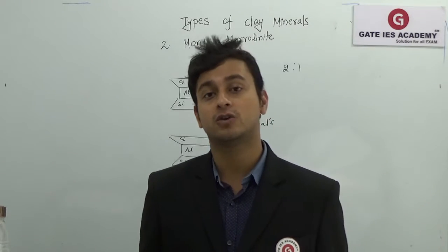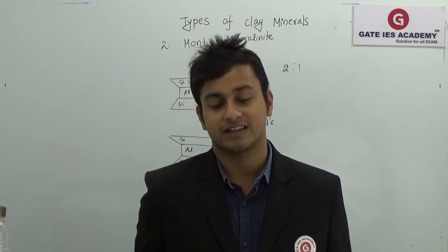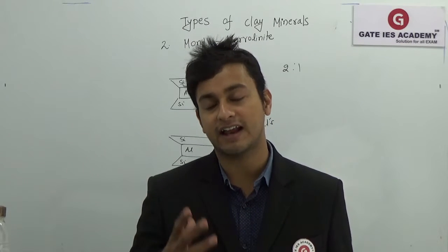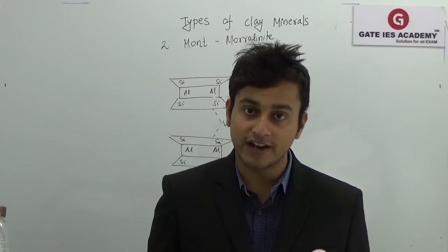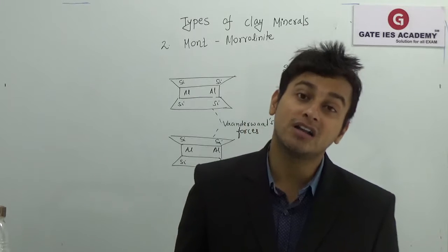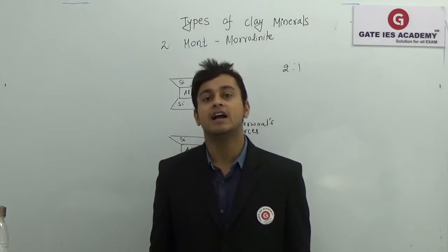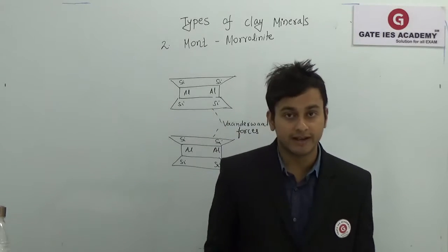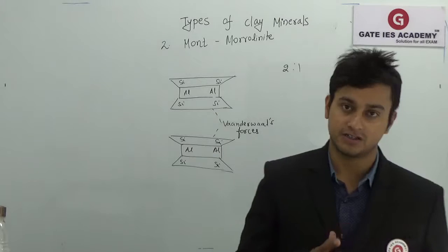They are said to be black cotton soil because these are highly active soils, because they have a lot of Montmorillonite in them. Moreover, cotton grows heavily in soils which have highly active components. Therefore, it is termed black cotton soil. Understood?